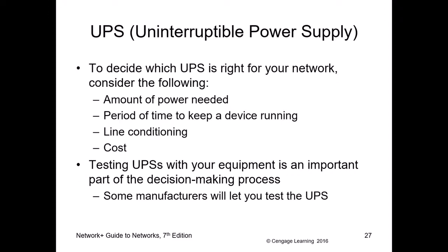Okay. Make sure that you know your UPS. Test your UPS every once in a while, because if you have no problems, then make sure that the rechargeable battery is still operational, because you don't want a blackout and all of a sudden the UPS fails. Maybe it looks like it's working fine, but if it's been there for a couple of years, the rechargeable battery may be dead. So periodically test it and make sure it's working properly.